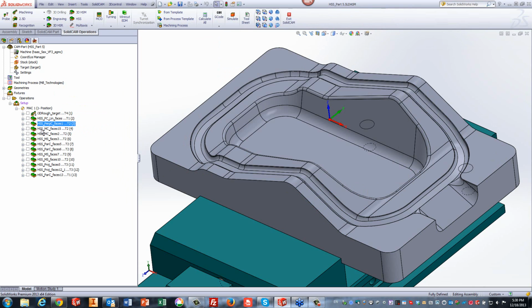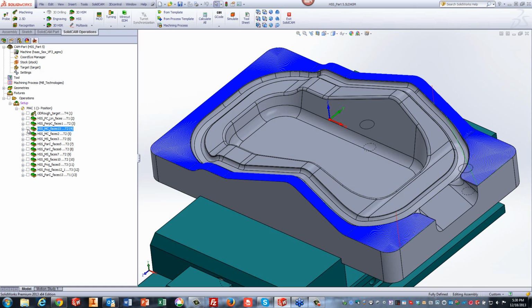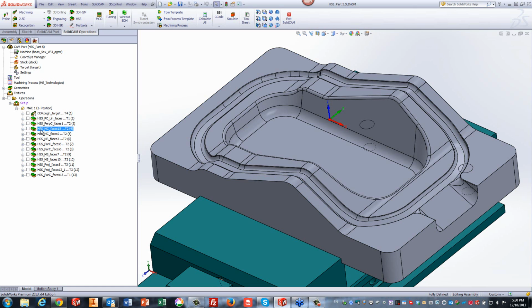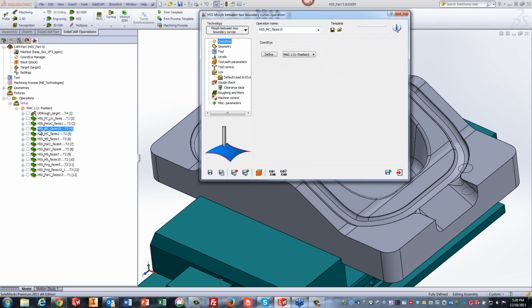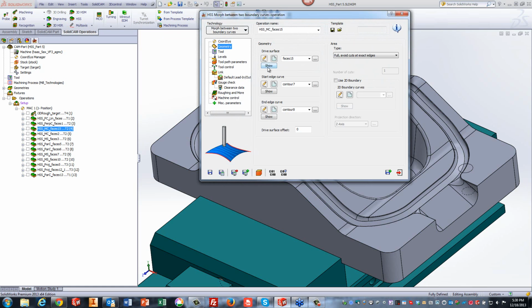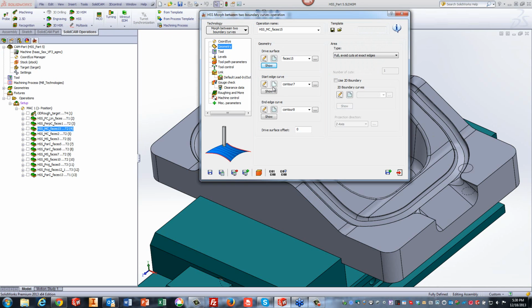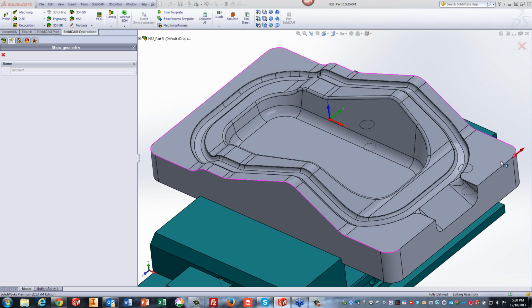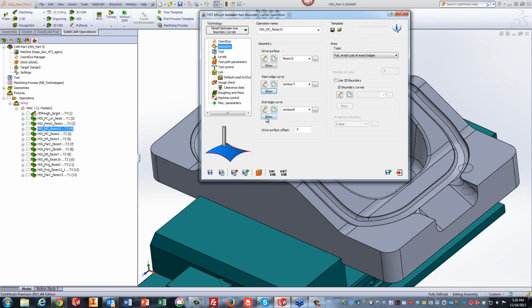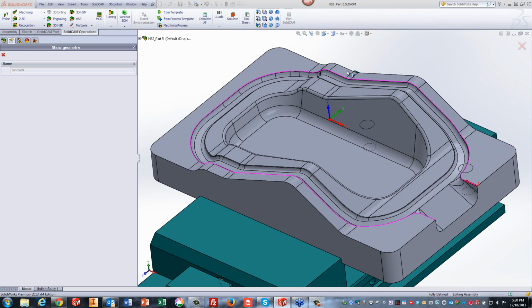One of them, another way I did that, if I show you the toolpath working on this surface over here, was using the option of morph between two boundary curves, where my geometry was all of these surfaces over there. My start edge curve was actually going from here around up until this edge over there. My surface going up until this point over there. And my end edge being this edge over here.